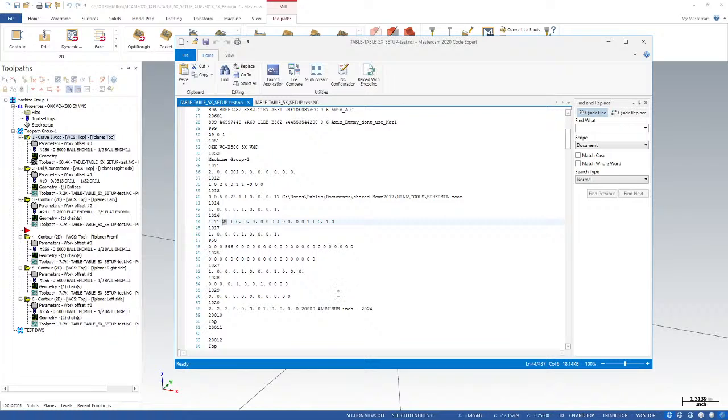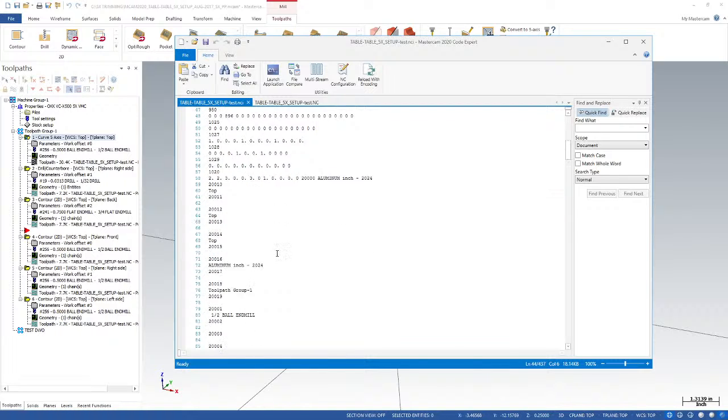All of this data is going to set the values of variables in our post processor prior to getting to the first tool change. And that's the important part, is we fill out the variables first, then we call the tool change, so we know what's the first move, what's the next move, what tool are we using, what's the RPM, all that kind of preparatory data.